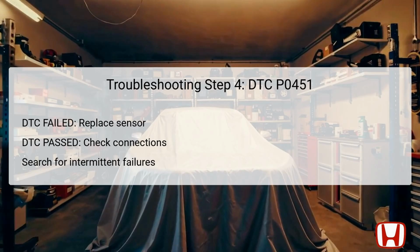If the HDS indicates that the DTC has failed, it is imperative to replace the FTP sensor. A failing or faulty sensor will not provide accurate pressure readings, which can impact the entire fuel management system. Conversely, if the HDS indicates passed, yet the vehicle has intermittent failures, the system should be verified for poor connections or loose terminals at the FTP sensor and the powertrain control module, PCM.